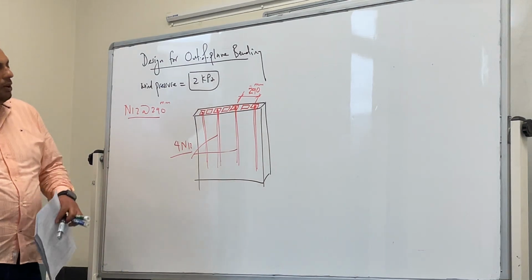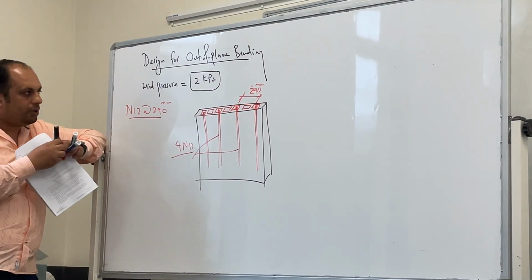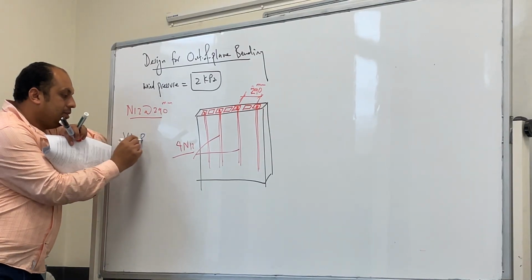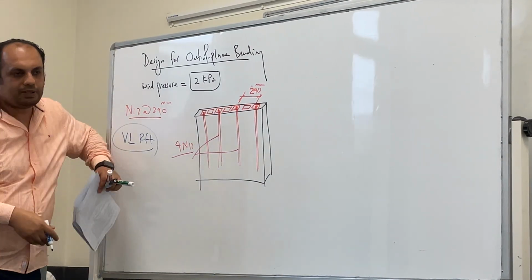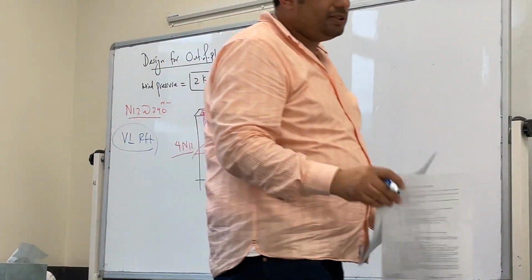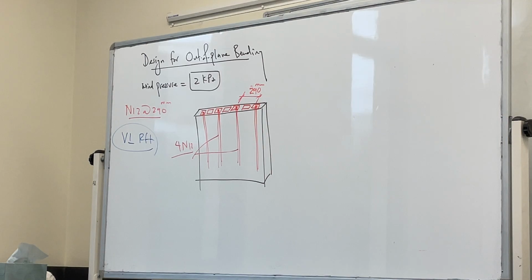Okay. So now, what we got? We have vertical reinforcement. This example has a trick here. If we read what he asked us to do, he asked to design this wall. Does he give any information? No. If we look to the question: design the wall for bending due to pressure of 2 kPa due to wind loading. Does he give anything? He only gives us 3 m. We have the height, we don't have the length, so we can go per meter. So what to do?